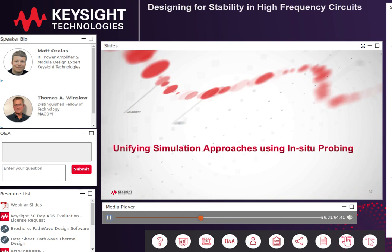So far, we've reviewed a number of analysis techniques for loop gain, return ratio, and driving point admittance. Now that we've got a decent arsenal of methods at our disposal for stability analysis, the problem now becomes simulation complexity, meaning that just deriving these metrics in simulation can be really costly and quite prohibitive. In this section, we're going to look a little more closely at a technique to simplify that.